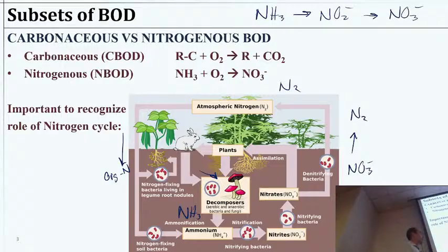Plants partake in this, microbes partake in this, animals that eat these things partake in this and then decompose, and all of that, right? So this is just a quick rundown of the nitrogen cycle, and in our wastewater treatment plants, we are often aiming to accomplish one or the other of these aspects, or at least needing to understand where the nitrogen is going, because when we discharge it, we want to make sure that A, there's not a whole bunch of oxygen demand because of all the ammonia, plus ammonia is toxic, so we don't want too much ammonia anyway, and we want to make sure we're not flooding our rivers and waterways with excess nitrogen that bacteria could use or other organisms like algae could use, which could cause some other problems.